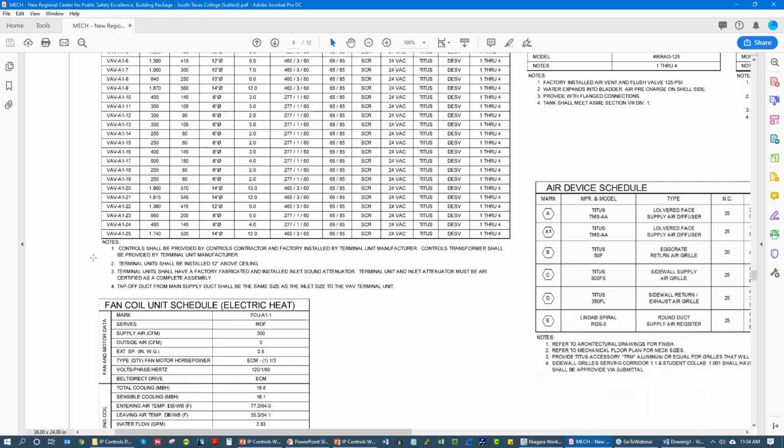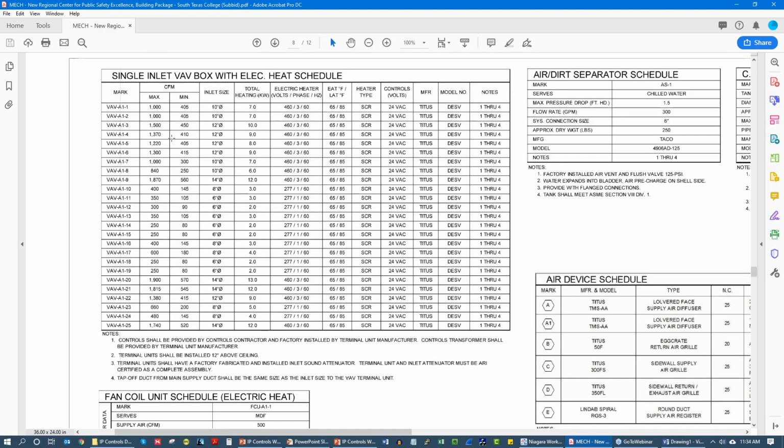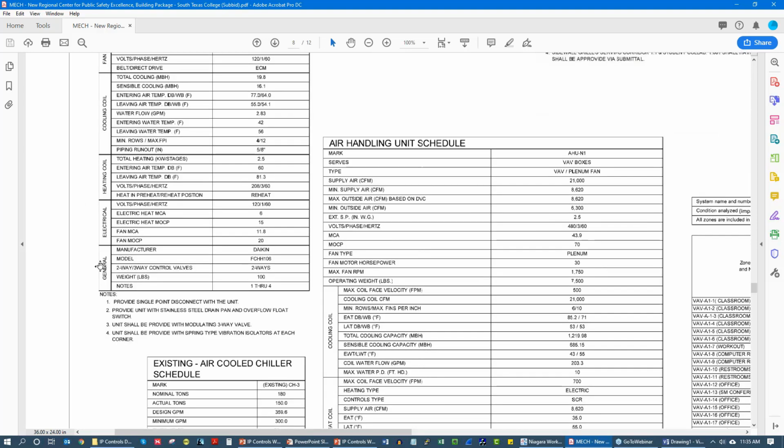I would typically recommend just submitting an RFI because at least that way you're getting contractual direction and you're avoiding them coming back later and saying, oh, by the way, this should have been ring instead of bus, which isn't that huge of a deal. I mean, it's one pull, but it's still one pull that you didn't price.